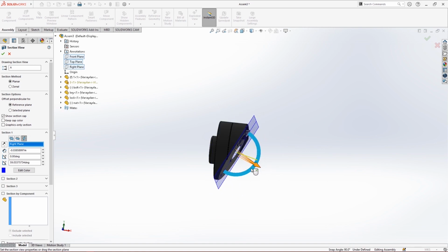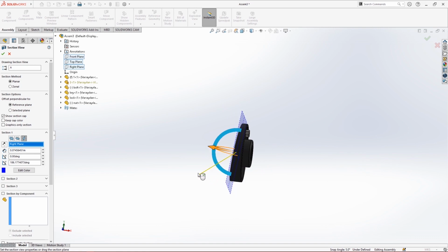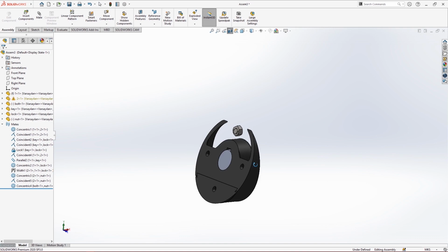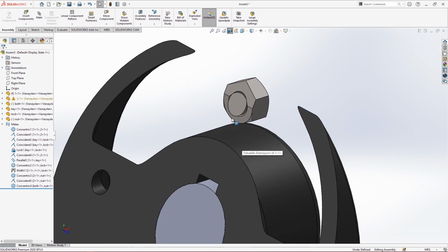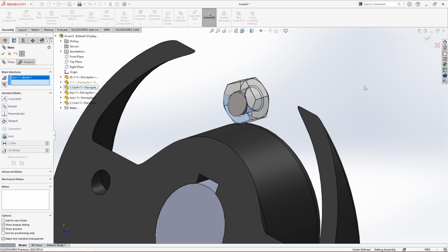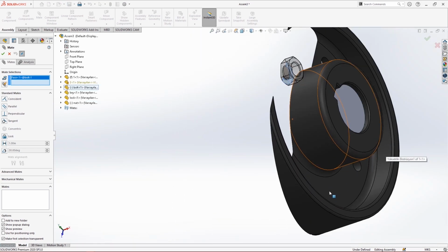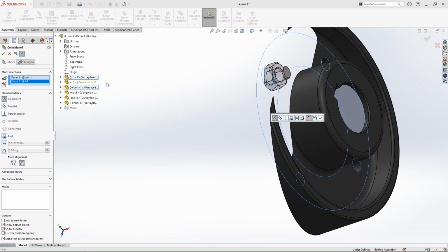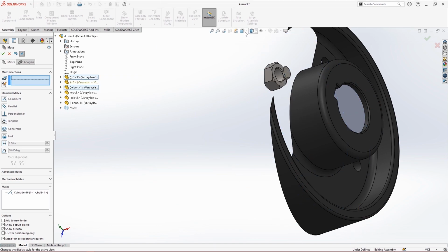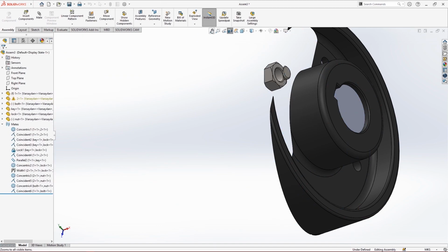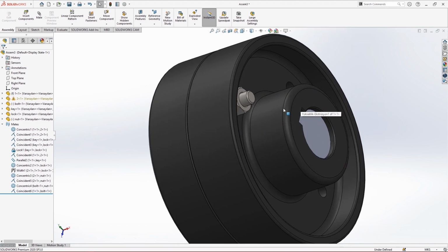I will do a little rotation right down here. Okay, this might work. Now I select the mate, as this is the bottommost point and this is the bottom, so it has moved. When I get out of the cross-section view, you will see the work has been done.